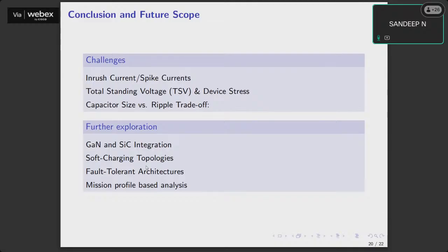The PV panel life is about 20-25 years, but our inverter lifetime is not that. The inverter would be 10, max 10 to 15 years, right? After 15 years, you have to either go for a repair or for a new inverter. So how to increase the lifetime? When you say increase the lifetime, the parameter that majorly affects it is the actual operating conditions.